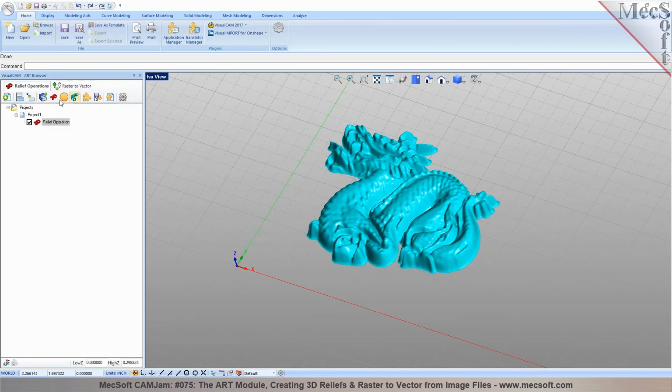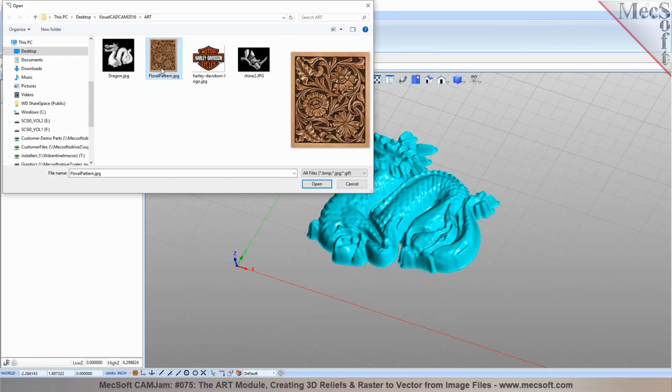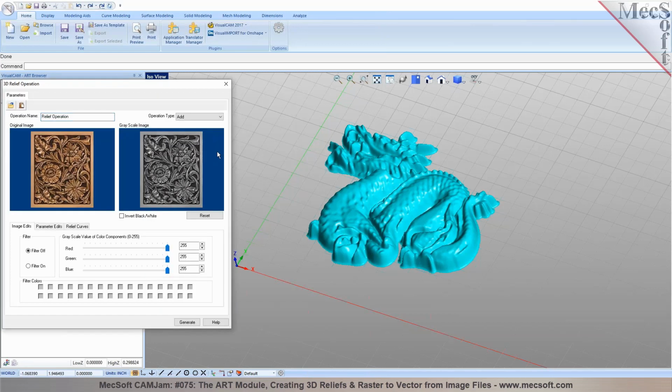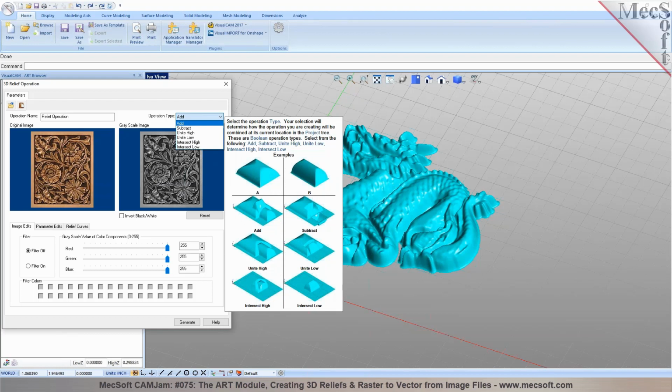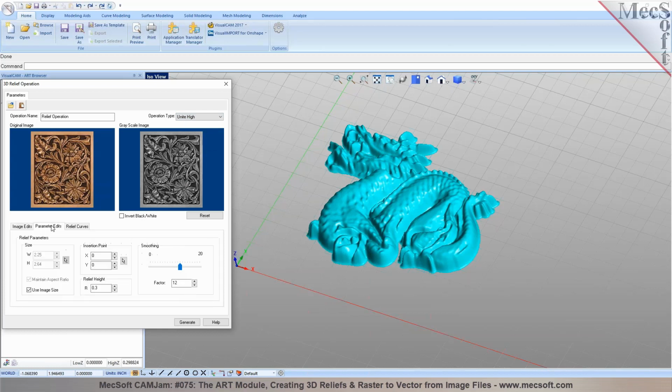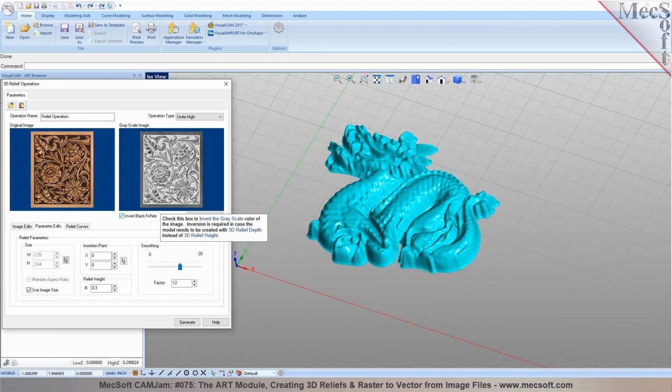No. Okay. I guess with regards to machining, would you want to use parallel finish? So parallel finishing with a ball end mill is kind of where you go, and would you want to do a second pass at like 135? Yes, I would change the angle for it, and I would definitely do that. So basically, you get a nicer finish. All of the scalloping that's being left from one cutting direction will automatically be taken care of when you change the direction of cut. And would you do roughing at all with art? I would, depending on how big the part is and if it requires roughing. I would definitely do that.